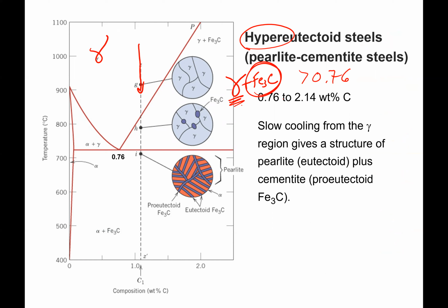So what we're going to be forming is cementite when we enter here into this two-phase region. So there's the cementite particles coming out again along the grain boundaries. So in this case, the cementite is our pro-eutectoid phase. Okay, so this would be similar in the eutectic system as beta, say, becoming our phase when we're on the right side of the diagram.